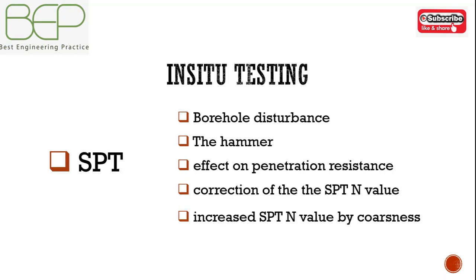The SPT N value is increased by soil containing coarse particles. Since most correlations have been obtained for sands, tests in gravels may give over-optimistic results. The SPT test is far from perfect, but it can be used in almost all soils, and a small sample is obtained for visual description. It is therefore widely adopted in practice, except in soft soil where very low blow counts result.